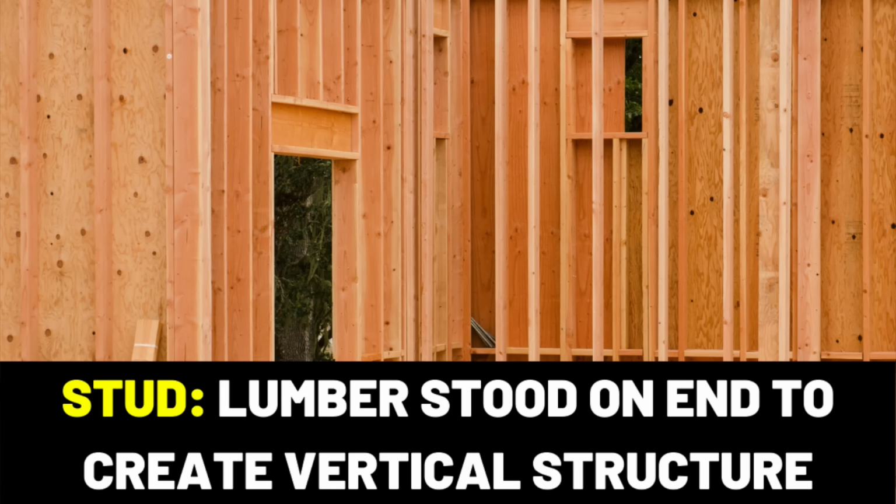Studs can stand individually, spaced out either 16 or 24 inches center to center, or they can be fastened together in groups known as stud packs. These packs sort of act as makeshift columns in our walls. They carry heavy point loads from somewhere above and transfer that weight down to a safe point below.